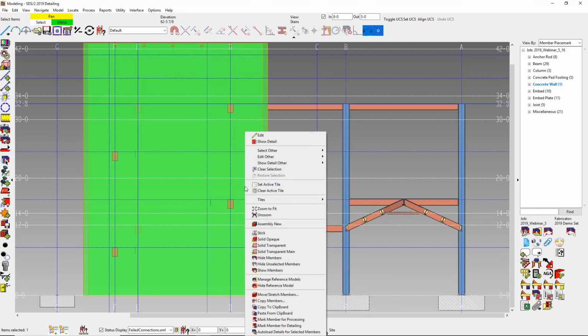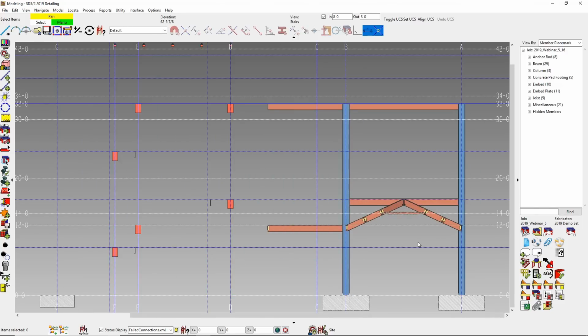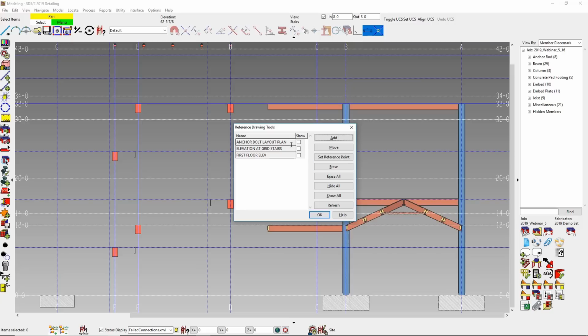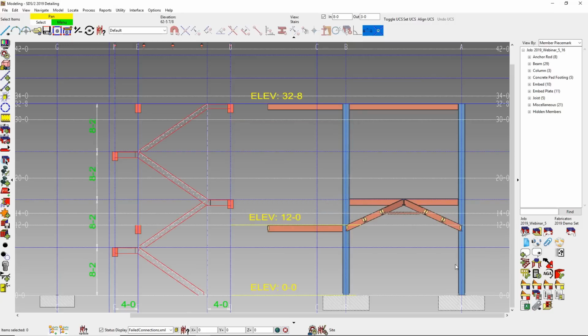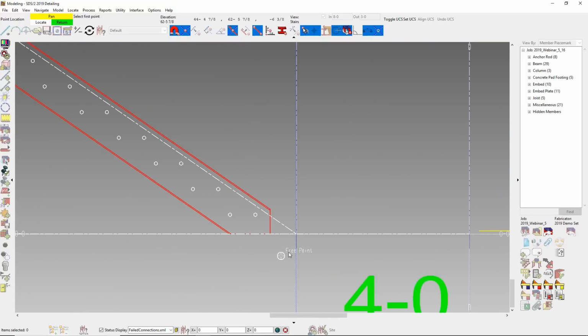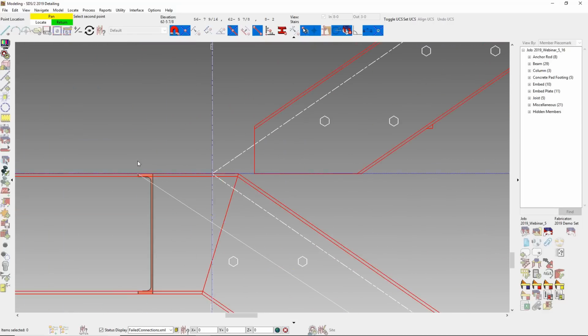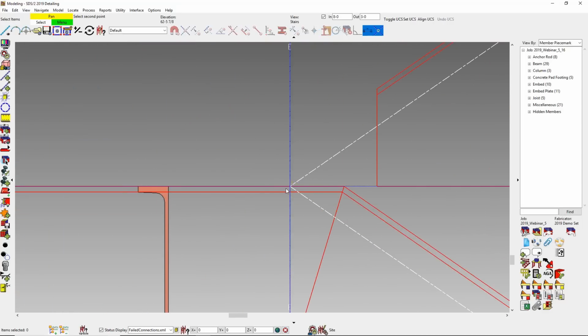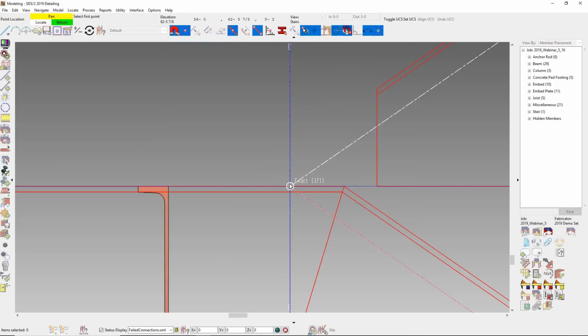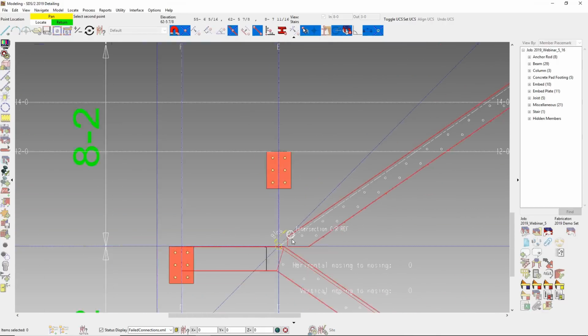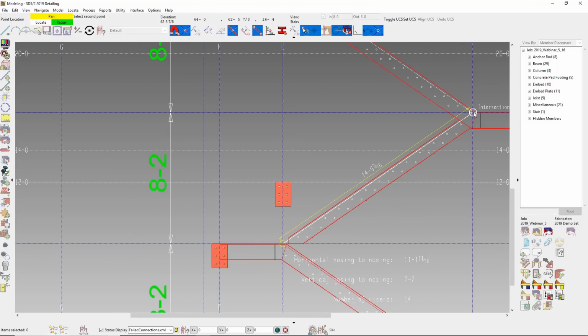So, keeping along the lines of secondary steel, I'm going to move on to the stairs and handrail. I'm just going to hide these members for now and then I can bring them back later on. Turning on the 2D drawings, like I did in the beginning for the beams and columns, is going to be a quick way to lay out what my stair stringers need to be instead of measuring for each elevation landing. I can add a single stair or a tower stair in the same view. Using the Stair Quick Add tool, I can add all 4 of my stairs in a single command.